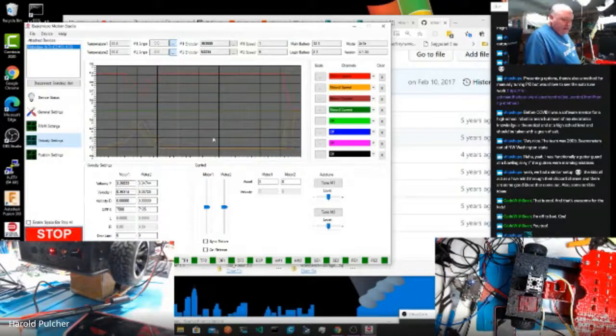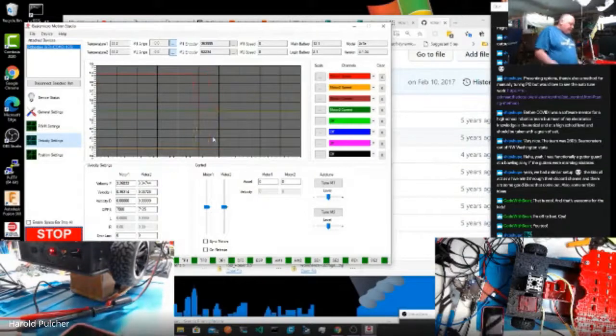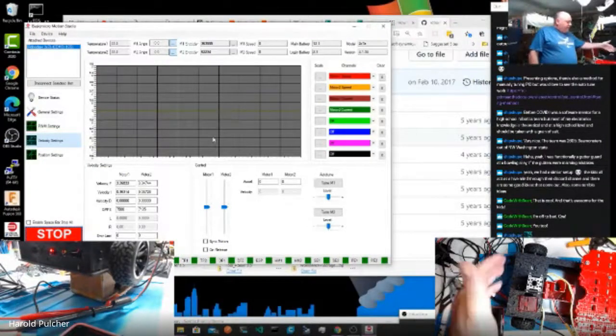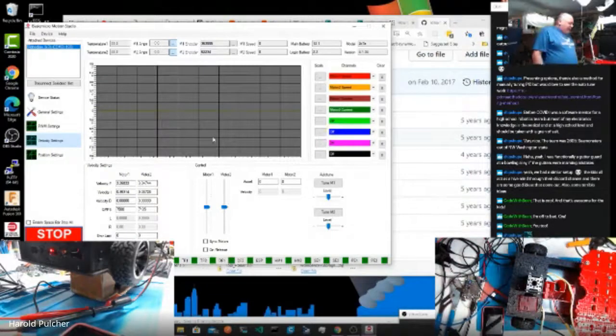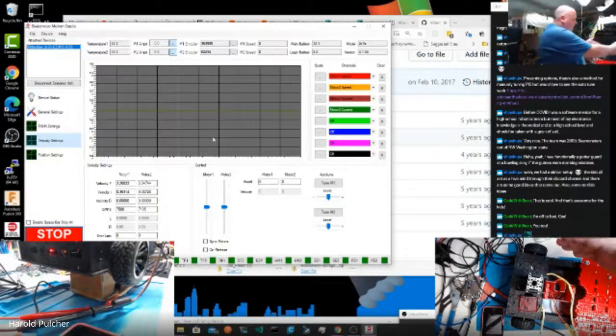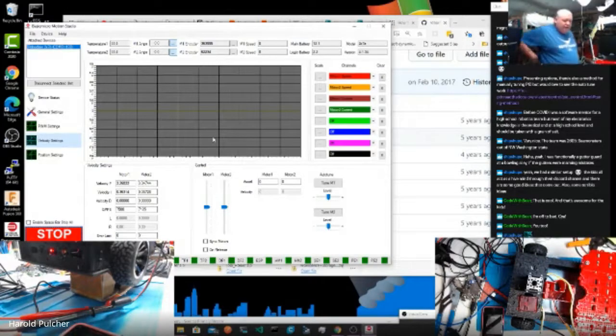You know, whether I'm going to do it in RC mode or do it in some kind of other way, because this controller, like I think Ray had pointed out, is really sharp. If I put it in RC mode, it knows how to do differential between the wheels, and it makes basically one joystick input forward and back, and the other joystick input left and right, and then it controls the velocities of the wheels for me on the fly. And I think that's where I'm going to start. I'm going to play with it, but there you go.